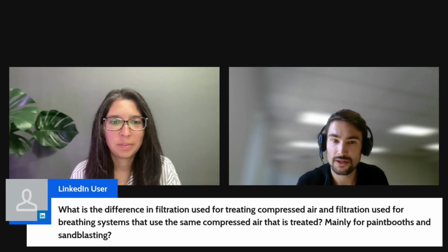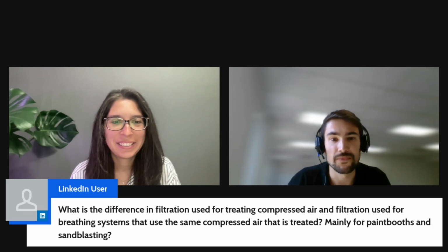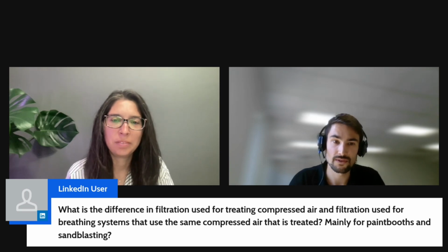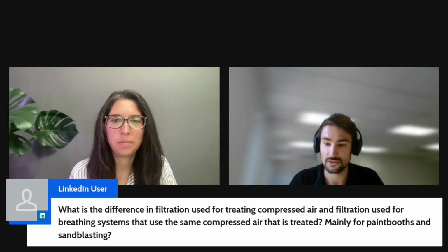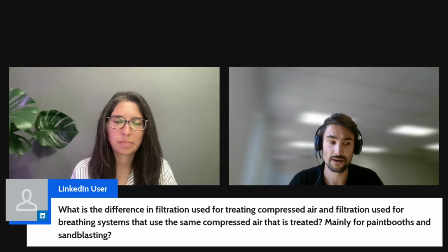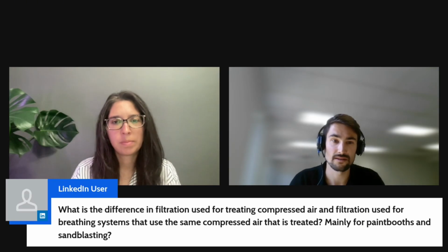Right. Perfect. And before you move on, we have another question here. What is the difference in filtration that is properly used for breathing air systems? Well, breathing air is a great topic. Breathing air is really important. Paint booths, sandblasting applications. You also have underground applications, for example, like sewer cleaning, underground mining. Those are situations where the worker, the laborer, is dependent on the air that comes in to be clean. And there are certain standards that cover that.